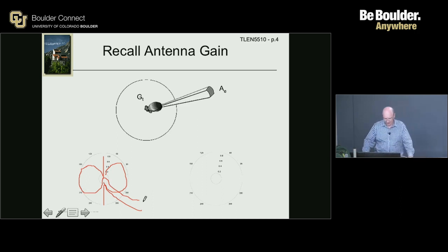And the dipole has a gain in that direction of its boresight. Anybody remember the gain of a dipole? 2.18 or 2.17. I forgot the exact number. It rounds to 2.17 dBi. So basically 0 dBd equals 2.17 dBi.